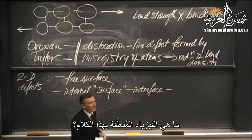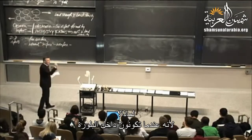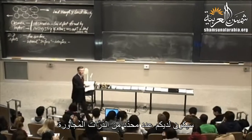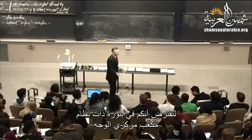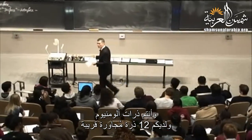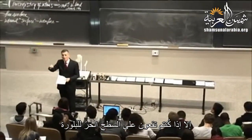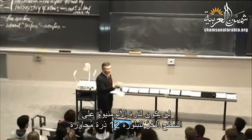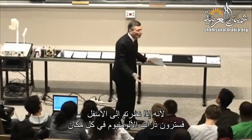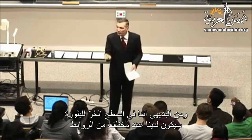So what's the physics here? Surfaces are high energy regions. Why? Because when you're inside the crystal, you have the prescribed number of nearest neighbors. Let's say you're in an FCC crystal. You're an aluminum atom, and you've got 12 nearest neighbors because you're FCC. Except if you're at the free surface. If you're an aluminum atom at the free surface, you don't have 12 nearest neighbors, because if I look down, I've got aluminum atoms all over. If I look up, I've got nothing. So axiomatically, I've got a different number of bonds.